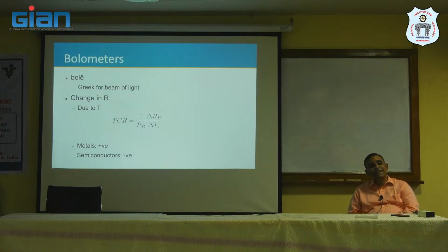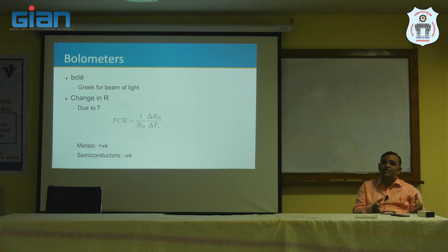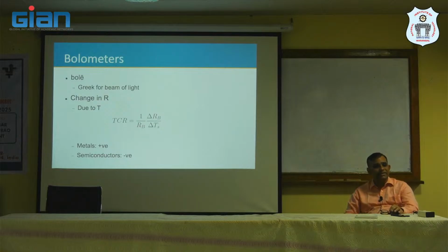So, the bottom line is that the more temperature you have, the more thermally generated electron-hole pairs are generated. In semiconductors, you have a larger number of charge carriers available to carry current. If more charge carriers come in, your resistance falls.